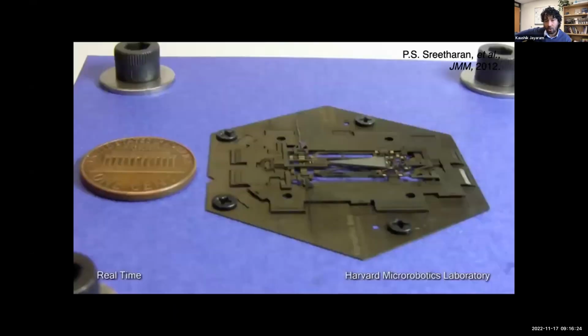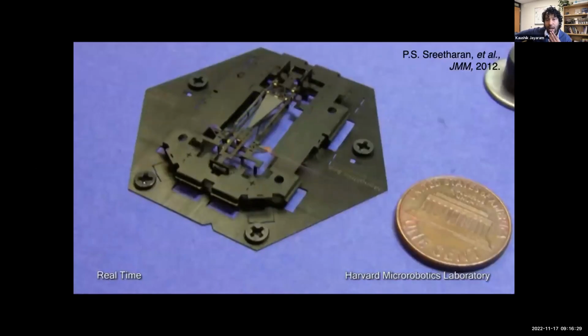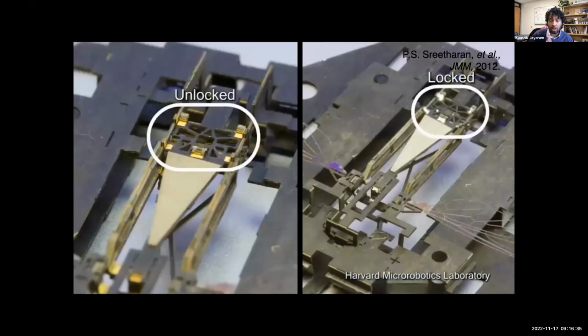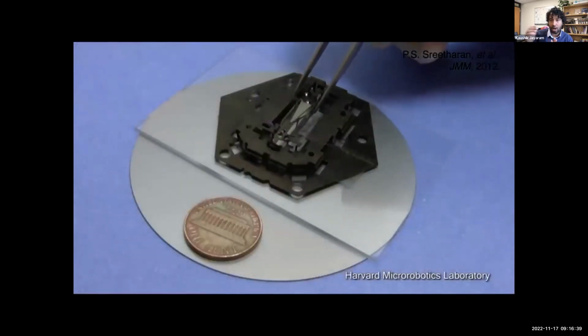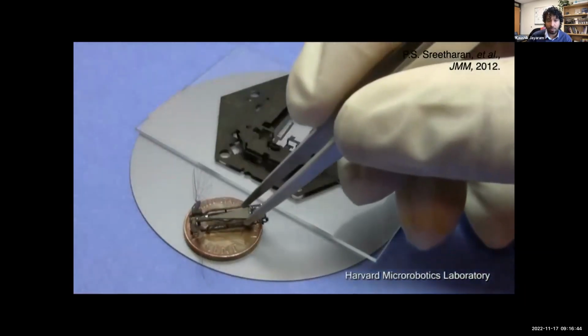So you can integrate your actuator, sensors, and wings in a flat planar approach, and then using a set of locked joints, you can pop the whole structure up, glue it in place, and then your assembled structure is released.